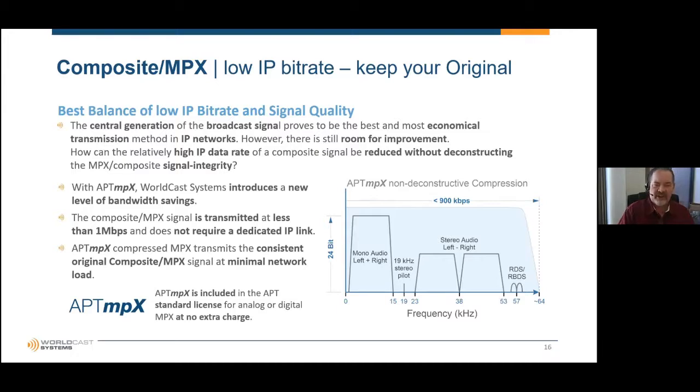It's a quasi-linear approach to compression, but it is packet-based, and so each packet contains all the information for a particular sample. There are some solutions that use a group of packets approach where you send a keyframe, or a key packet, and then subsequent packets transmit only the differential data between that packet and the packet that preceded it. In those types of algorithms, as in the audio realm, where they would be called frame-based algorithms, if you lose one packet, your actual loss of the stream is going to be more significant. You can lose many packets and have a more noticeable interruption in the audio.